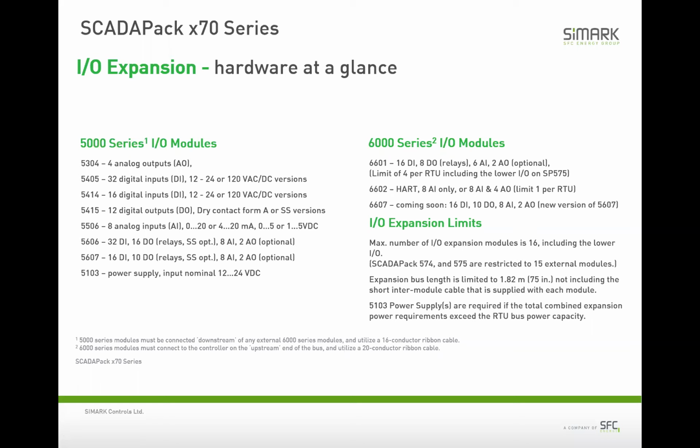Expansion number of modules you can add in, about 15. If you already have one in the SCADAPack, like with a 574 or a 474, then you've got the ability to add in about 15 other modules, with the limitations that you see here: the bus cannot be longer than about 75 inches in length, and you might need to incorporate additional power supplies depending upon your expansion module mix, and that's something we can help you with at the time of configuration.